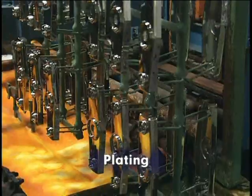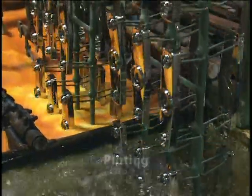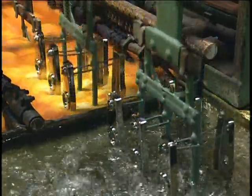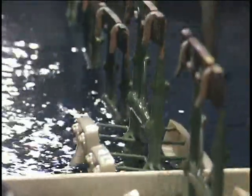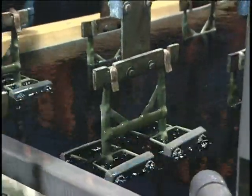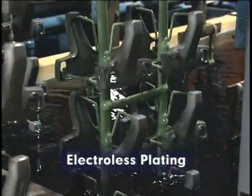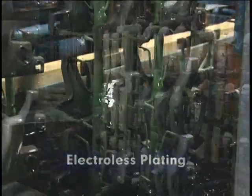Plating is the chemical or electrochemical deposit of a thin metal layer to the surface or substrate of the plastic part. Plating requires the plastic parts to be electrically conductive. To achieve this conductivity, the plastic parts are first subjected to an electroless plating operation.